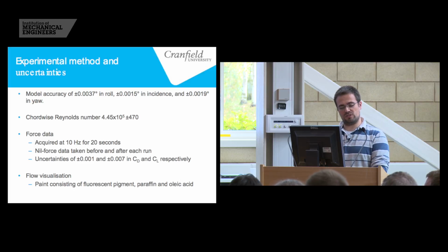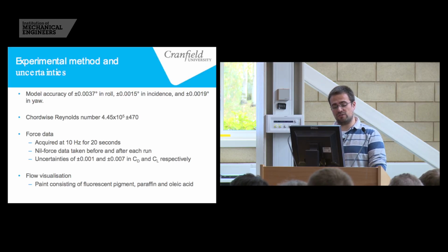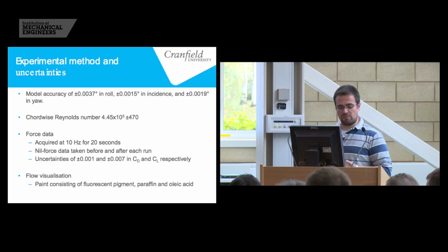We did try different logging frequencies, but in the end we found out that 10 hertz did not make a significant difference, especially in the undisturbed cases. In the disturbed cases, there was a slight offset, but about 95% of the runs were repeatable. No force data was taken into account for any deviation, and the uncertainties were calculated based on the different parameters that you could set up. So wind speed, positioning of the wing, height, incidence angle, all the parameters that would influence it.